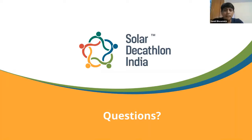Maybe if I can add here, the ambient humidity is an important factor. If you're in a coastal area and you have a lot of humidity around you, it automatically excludes a certain kind of system. For example, you can't use an evaporative cooling system if it is already very humid outside. So it's essential to understand.